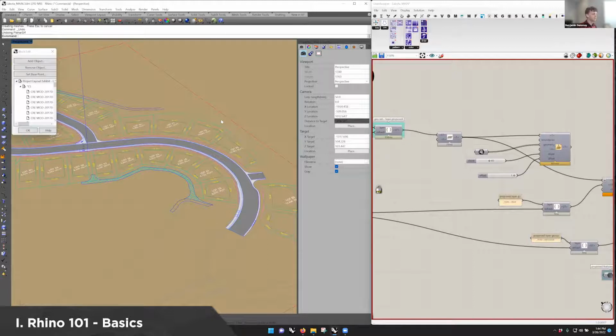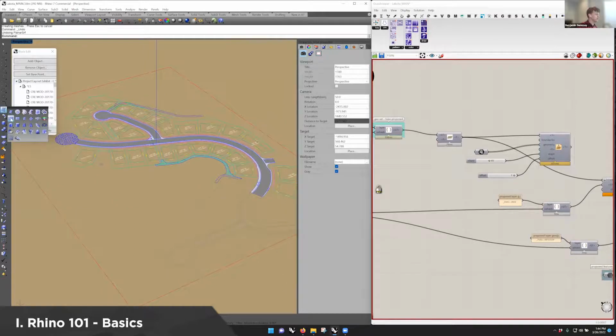But a lot of times, if it's coming from a survey, where they've created lines from the points they've pulled, the points don't always match up perfectly once it comes into CAD software. So when you're dealing with things like curves or edges of pavement in order to split your areas up, it's good to double check some of that, or just lay out a big surface across the whole area that you're dealing with.